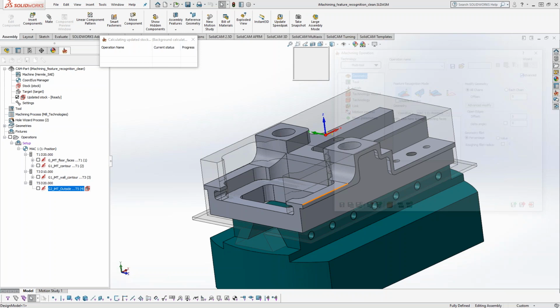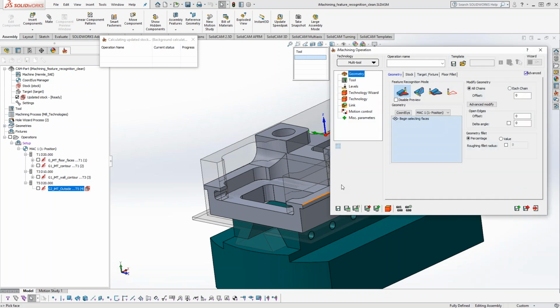And one thing you'll notice is I really don't use copy and paste now. I think you absolutely can still use save and copy and paste, but the iMachining operations are so well defined and so easy now that it's very easy just to create a new operation every time. Pick your geometry. We find all the levels for you automatically. Pick your tools in Multitool, which is really easy, and you more or less have your operation all set up.